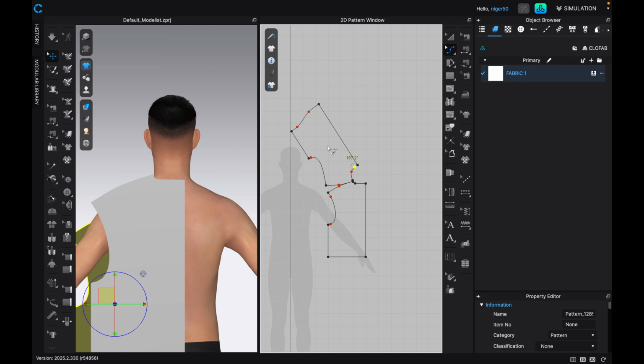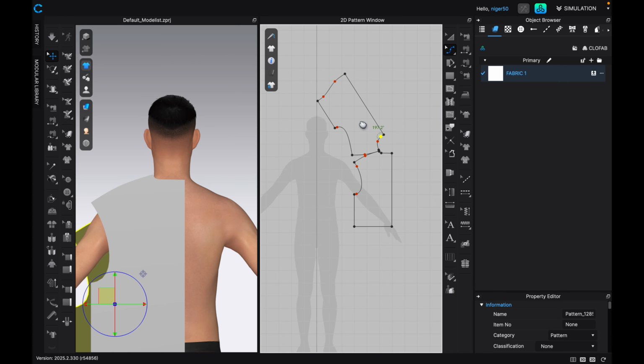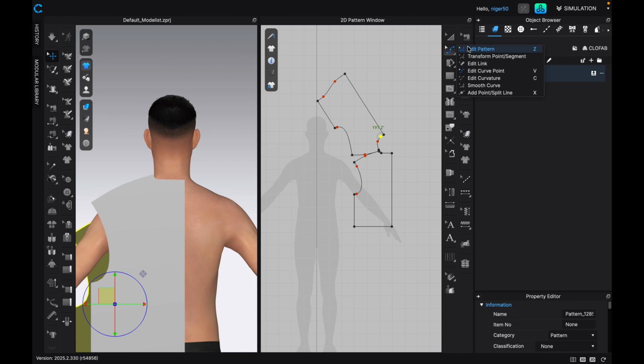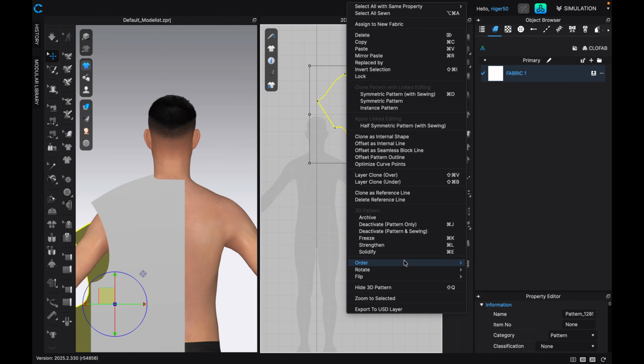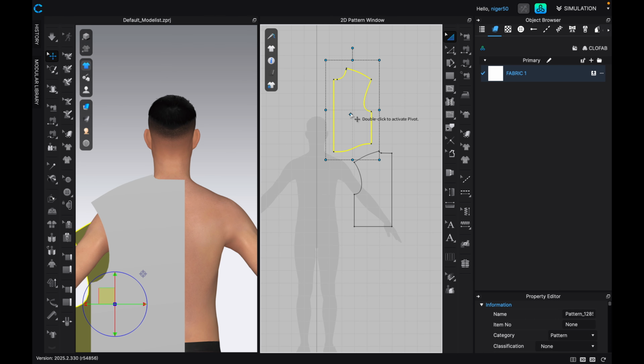Let's unmatch. Now what we'll need to do to reset this, to put this back to where it was before, is to, first of all, leave this. We're going to press Z. We need to leave this totally. So we're going to click on this, right click and then go to other. We set along grain direction and then we have it back to its normal settings.